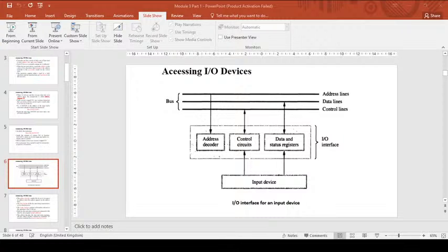A line of characters is entered through the keyboard and the screen has gone to the next line for the display, right? So it has to continuously check the entered character, which will be present in R1, with the ASCII code of the carriage return in the keyboard. If both are the same, the program has to end. If they are not the same, again read the next character, branch to wait k, then display it. Again store it and check it with the carriage return.